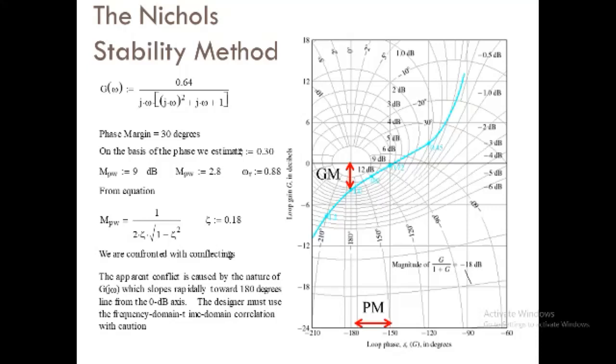Now we are moving towards the y-axis representation. This is our ordinary scale, which we are familiar with. In graph 1, we plot the magnitude in dB on the y-axis, and in graph 2, we plot the phase angle in degrees on the y-axis using suitable scales. The transfer function can be written as a ratio of polynomials. It must be factorized to obtain the general form.